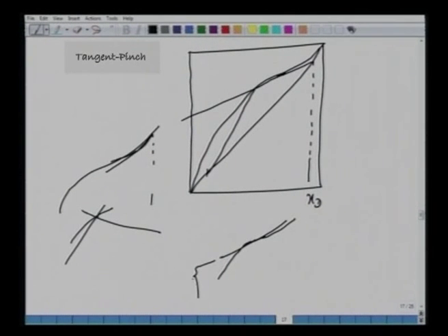So if you take the intercept, this will give us xD over R plus 1. From here again we take 1.5 times R minimum, so R operating equals 1.5 R minimum. So very often when we have this pinch, one has to be a bit careful and look at the shape of the curve where the operating line can make a tangent. This is very similar to what we did in the case of absorption.